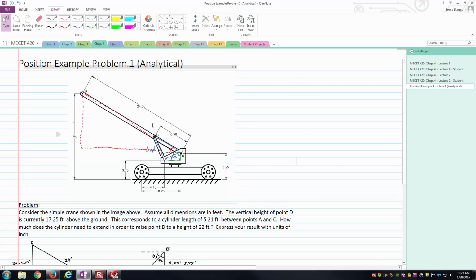As far as what I'm going to start sketching, I need to lay out the initial configuration, or initial position, of the mechanism. I'm first going to locate points A and B. As you can see, points A and B are fixed to the frame part if we just talk about the two-dimensional motion, the raising and lowering of the crane arm. We can watch the motion of all the other pieces as they move with A and B as fixed references. It's part of the frame for us.